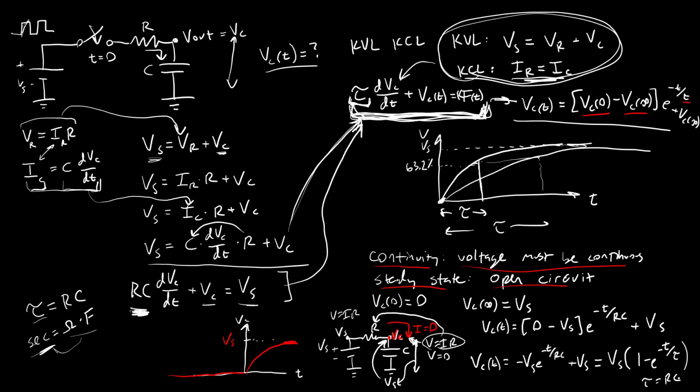So there you have it. All of that work to arrive at this final equation describing the time response, or the step response, of an RC circuit to a step input where you are either closing a switch or driving this with a square wave.